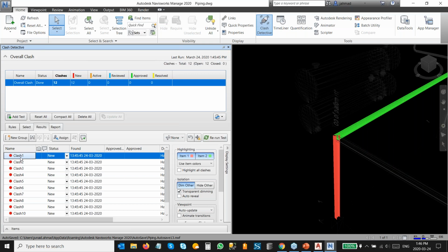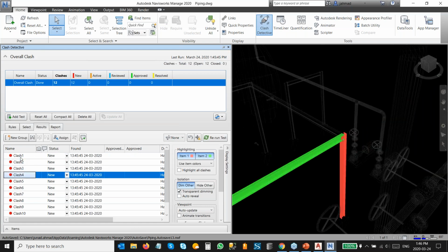you know that you can go back in the piping drawing, in the structure drawing in Plant 3D, and you can start making some adjustments here by using the built-in miter cut member or cutback member tools available in the structure module. So you can adjust them, and obviously we don't have time to go and resolve each and every clash.